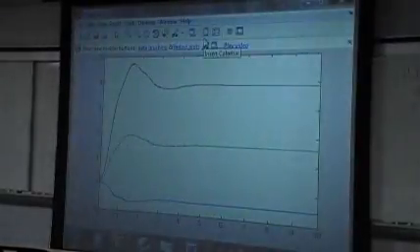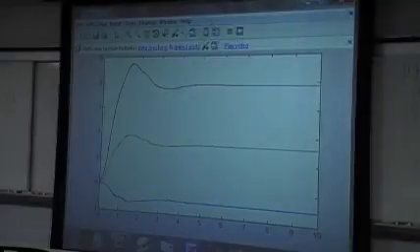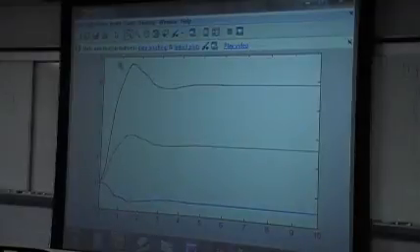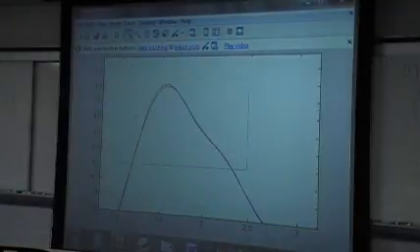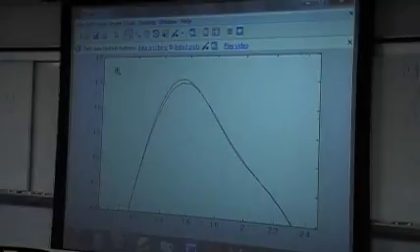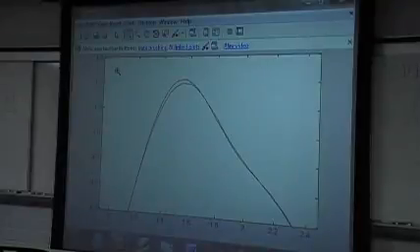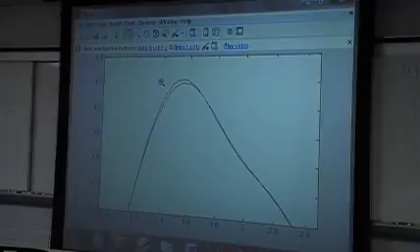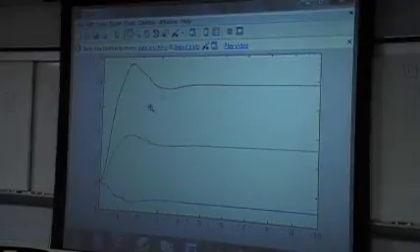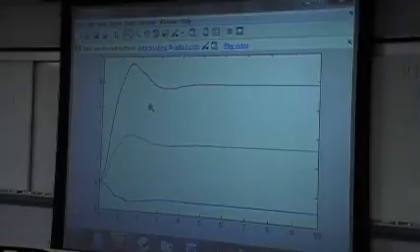And we may see that the results of the 2 cases are nearly the same. So we say that the results are acceptable. If you are not happy with the result here, you have to further reduce the relative error tolerance to even smaller numbers, 10 to the power of minus 15 or even smaller. But virtually we will say that these results are acceptable, so we say that they are correct.